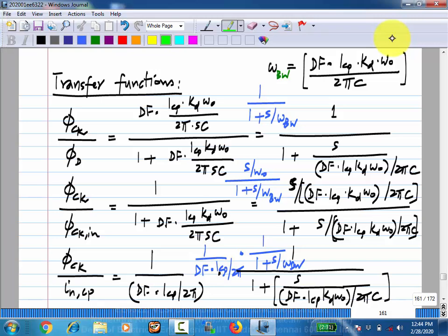What is the trade-off now? No. I mean, it gives you the same bandwidth, right? I can use maybe C is 10 picofarad and I can use a microampere, or 100 picofarads and 10 microamperes. What difference does it make? No. I mean, if the bandwidth is the same, why does it take more time to turn on? Noise is the only thing, right? So if you use larger current, you will have less phase noise that is generated in the CDR. Okay. So in principle, as long as you maintain the ratio the same, it will behave in the same way. Okay.